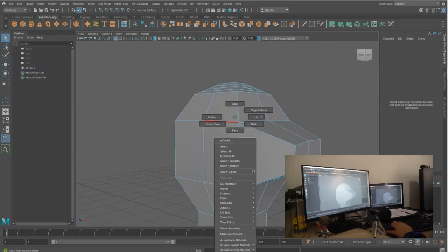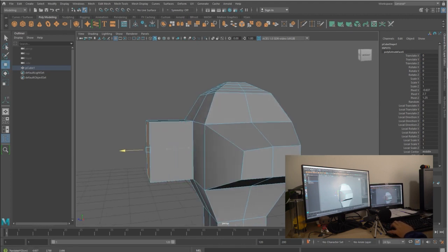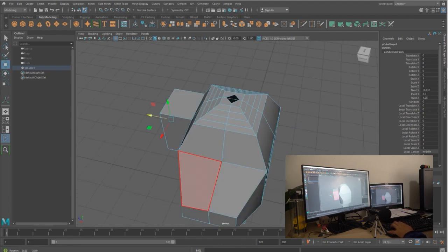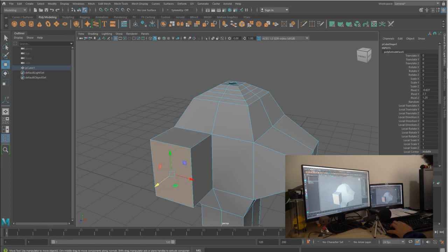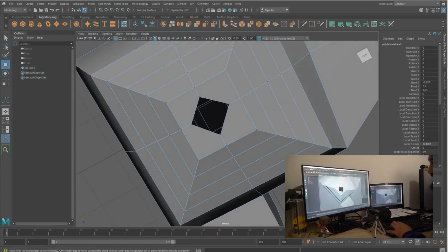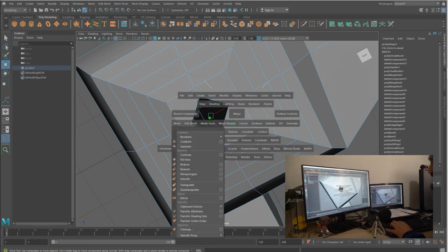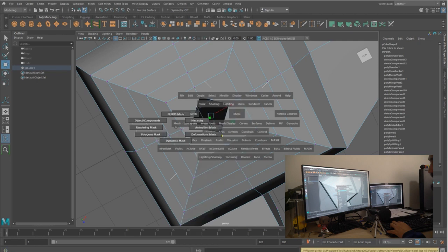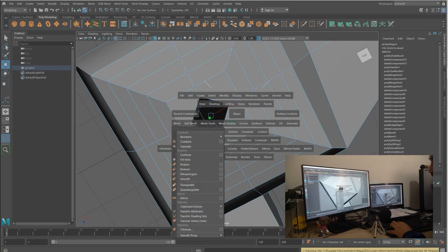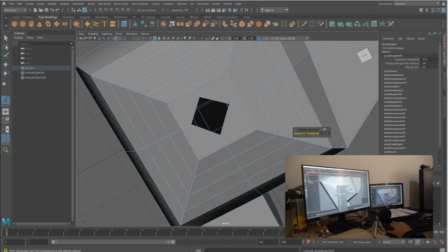We are here, we want to extrude here, Control E, rotation, translation, and we can transform. We also want here to have all those vertices into one vertex. We select the 4 of them, press space, go on mesh, select edit mesh, and select merge.